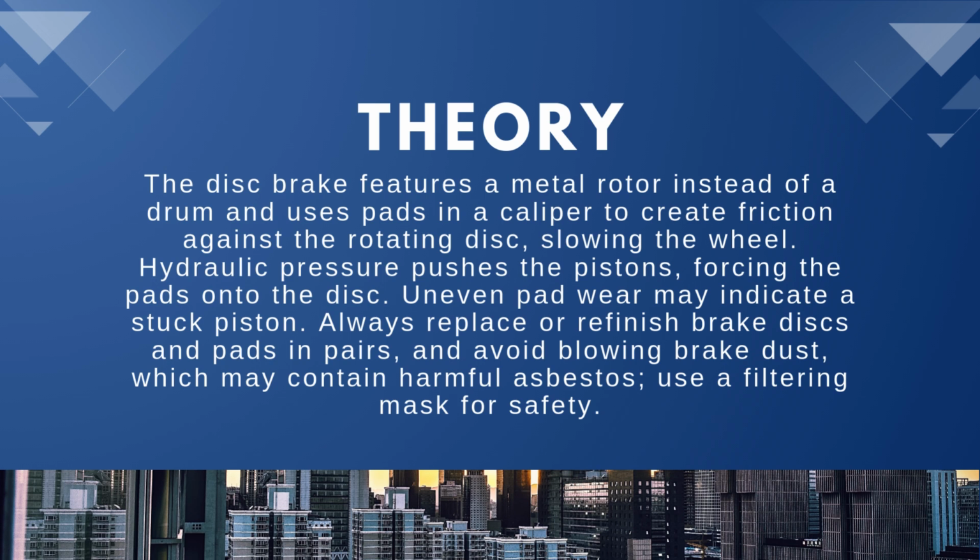Always replace or refinish brake disc and pads in pairs, and avoid blowing brake dust which may contain harmful asbestos. Also, use a filtering mask for safety when doing service on brake pads.